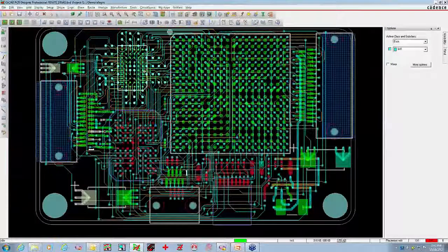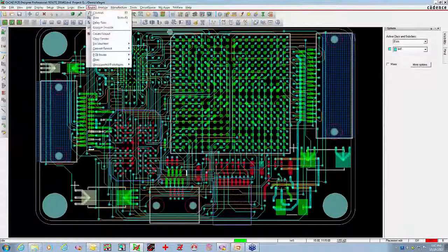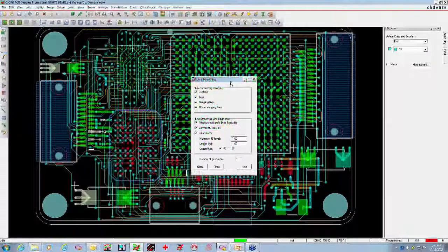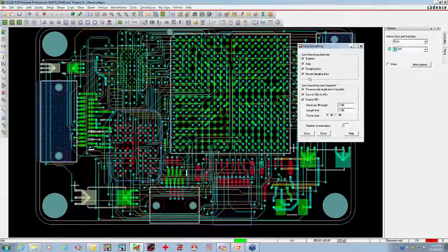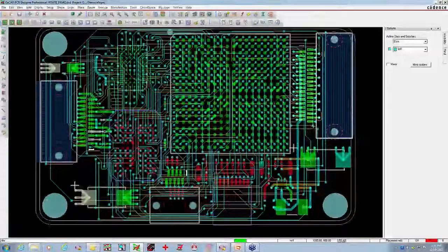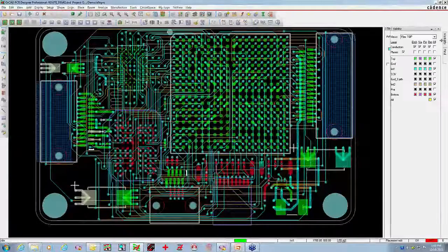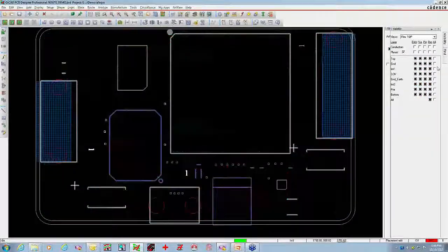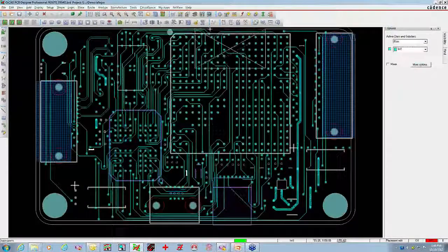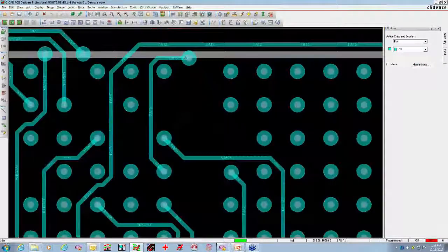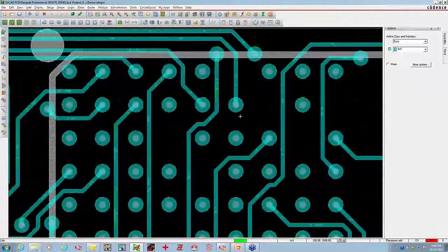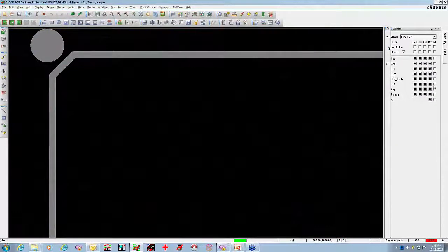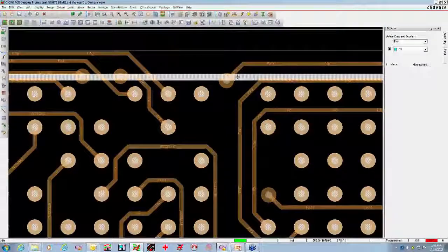So let's go ahead and employ some of my glossing techniques now. If I go to the gloss menu, I'm going to go to my line parameters, and here I can pick and choose those things that I want to try to eliminate. So I'm just going to go ahead and gloss it. It'll do a little bit more optimization. If I go up and I look at that layer that we looked at in the router, and I think it was up in this area right here. Yeah, so I think it was this trace right here.